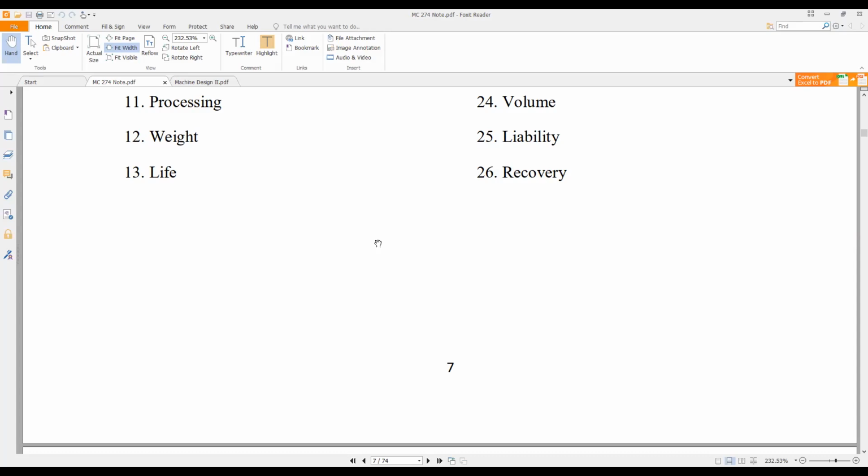Now, the essence of the bending moment: when a particular member is under the application of some load, that member is prone to fail at some point along it, and is likely to fail at the point where the bending moment is highest. And so in design, that point where the bending moment is highest, we consider as a stress concentration point. Therefore, special attention has to be paid to that point in order to prevent that part from failing at that point.